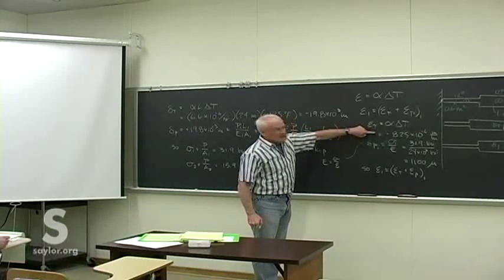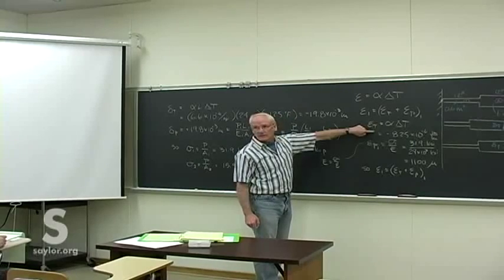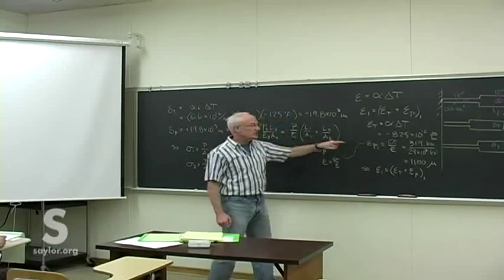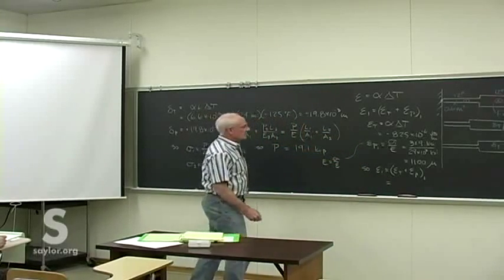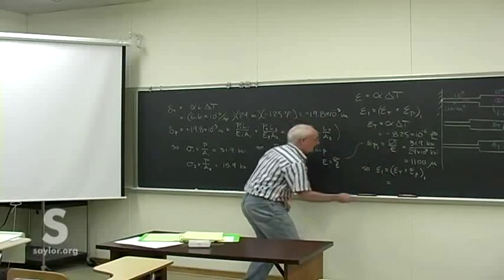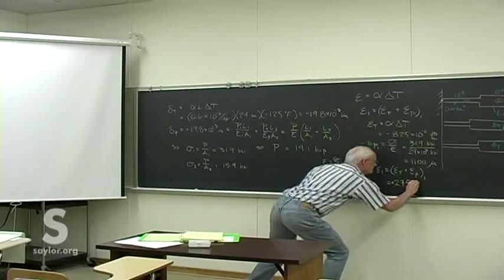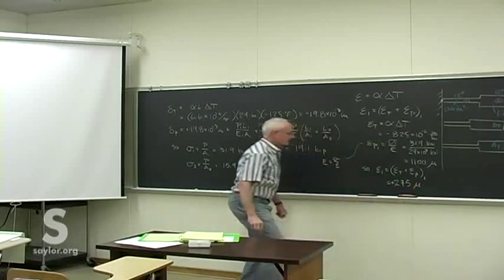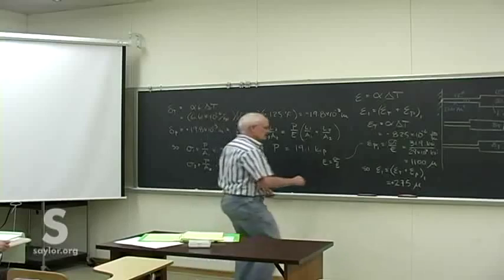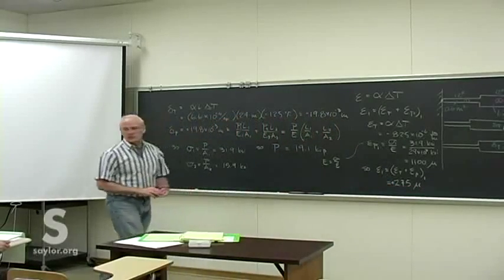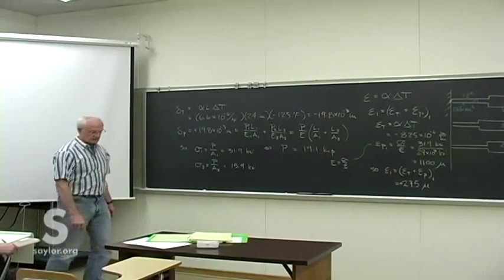It's the strain due to the shrinking from the delta T, and then the mechanical strain due to expanding it back, leaving an induced strain of the two of these added together, and that is the 275, plus 275 micro inches per inch, induced in the piece due to the thermal and the mechanical strain in just that first section.